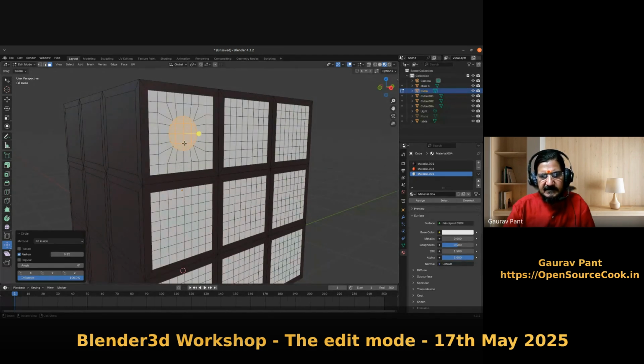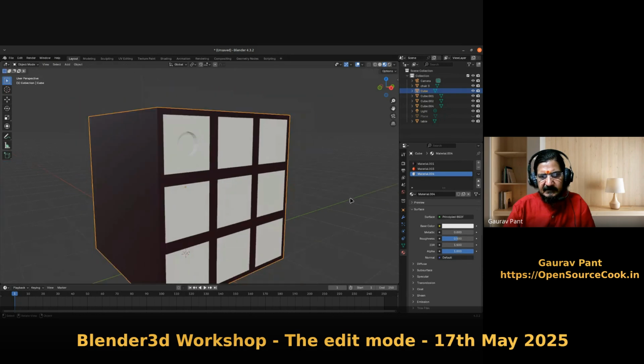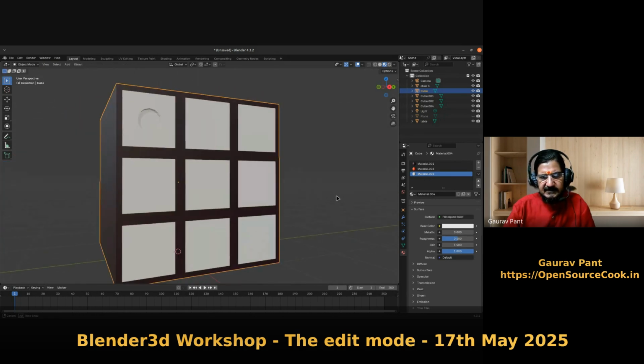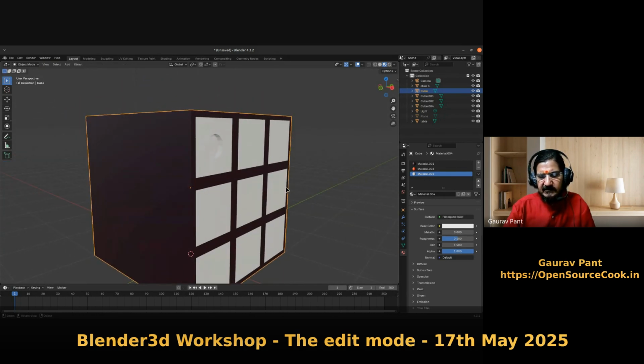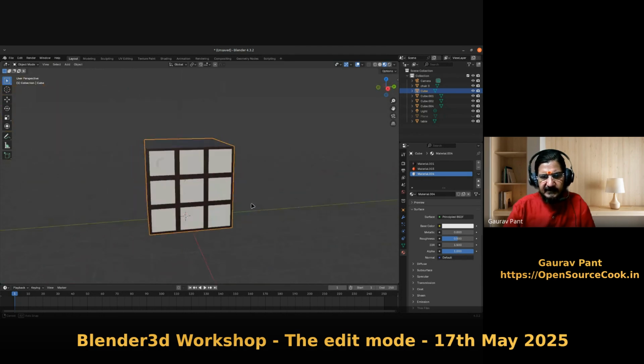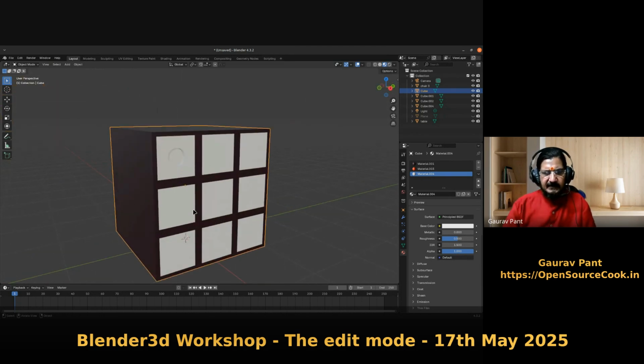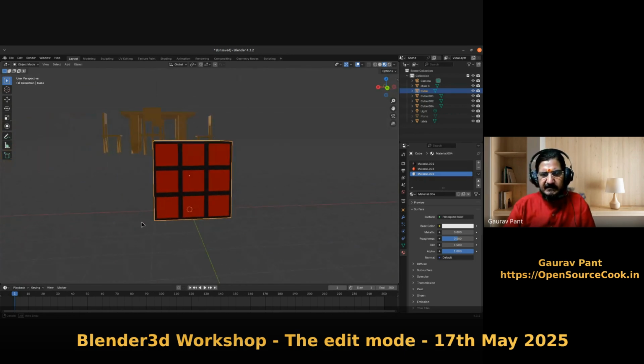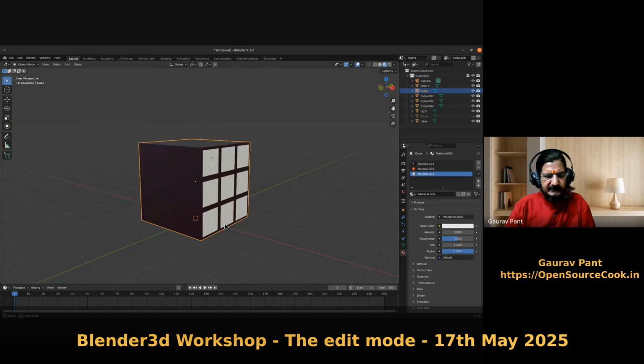The circle is created, then you can say dissolve faces, and now you could do your extrude operation on this. This time we put it inside. So what we have is a face which has a circular area in between. Right. So there are a lot of tools and techniques available here in Blender to get these things done, and you have your objects.